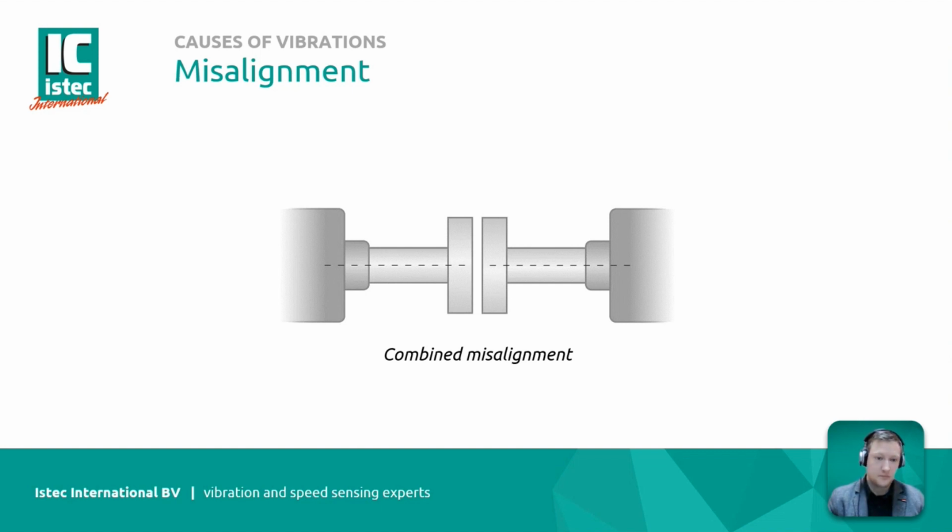It can excite natural frequencies like unbalance. It can cause strain on surroundings, pipes. So misalignment is a very important cause to keep in mind when a machine is being placed, and aligning the machine is very crucial for a proper operation of the machines.